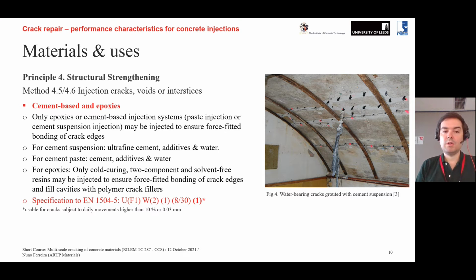Perhaps the most interesting part of epoxies is that although they don't really accommodate long-term movements, they can accommodate short-term movements in the sense that they are kind of dynamic resistant. So when you are specifying epoxy materials, you can see that there is a fifth group over here, where we can actually be more precise and say that you want the material to withstand daily movements up to a certain percentage.